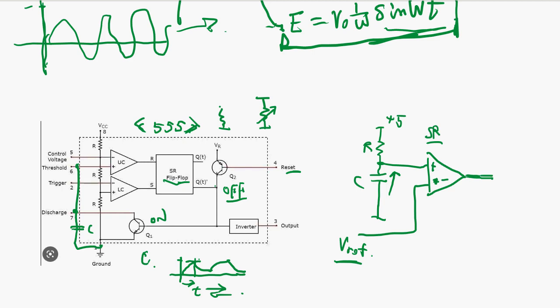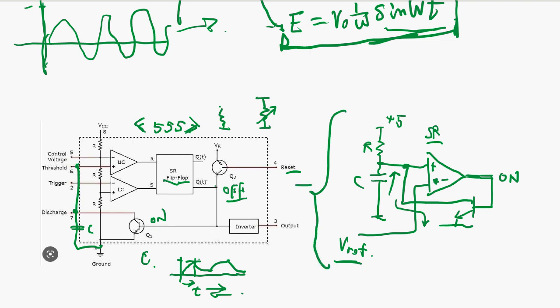It was negative and suddenly turned into positive. So the transistor turns on and discharges. As soon as it's discharged, it starts accumulating voltage again. This simple circuit is improved with a few more considerations. That's the 555 IC chip.